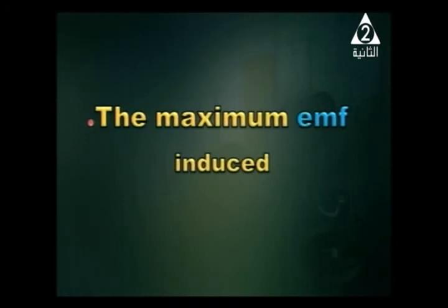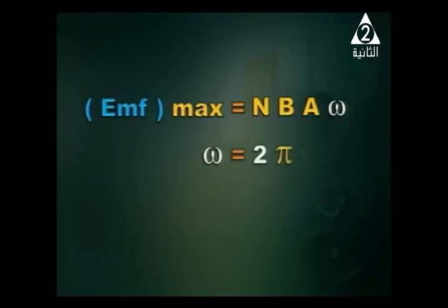the maximum EMF induced. Okay, EMF maximum is given by the expression NBA omega. Omega equals 2 pi f.